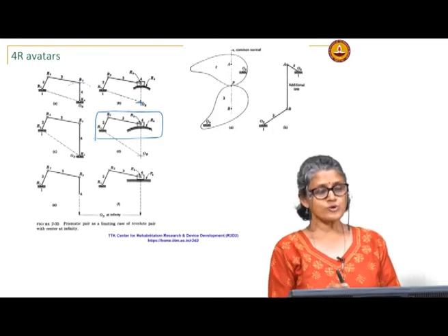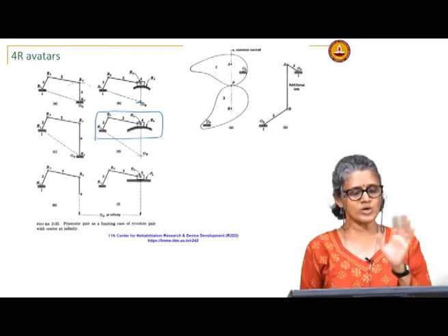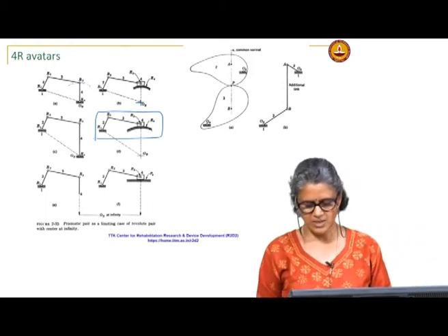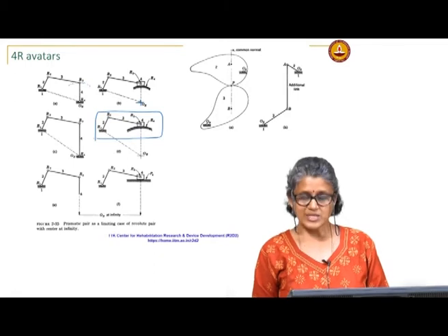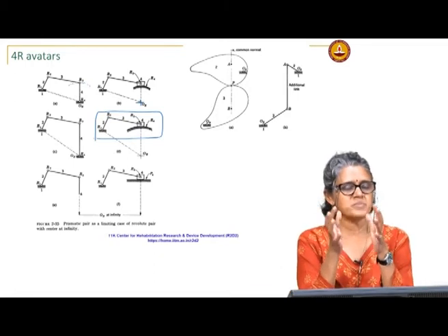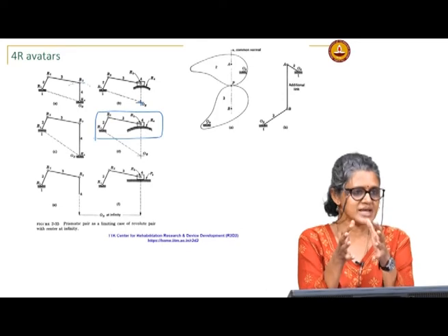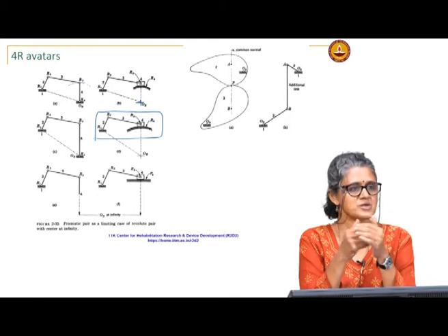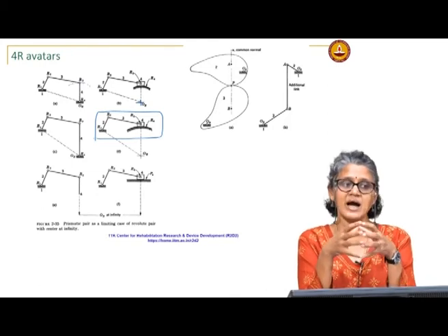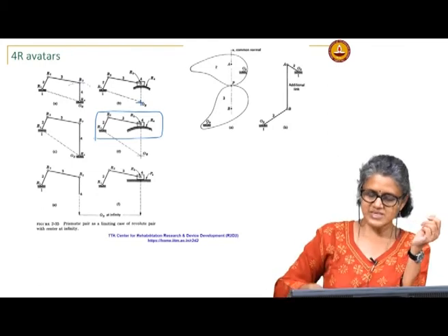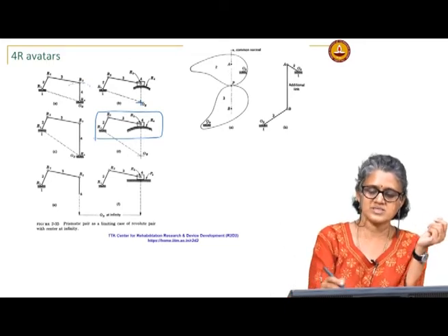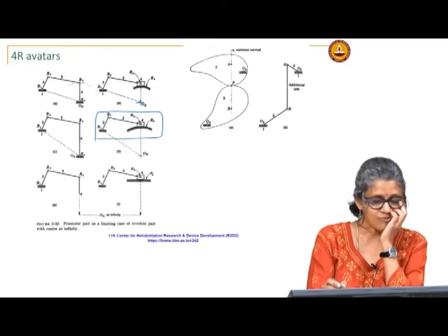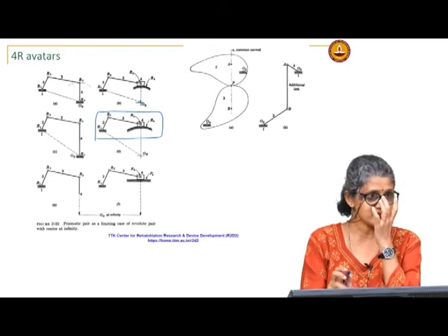This is even more useful when we have what we call kinematic equivalence, where the two linkages are equivalent for the purposes of, say, calculating velocities and accelerations. This kinematic equivalence is very useful, especially when you use mechanisms that have higher pairs in them. So, you take for example this cam driving another follower that has this complex shape.